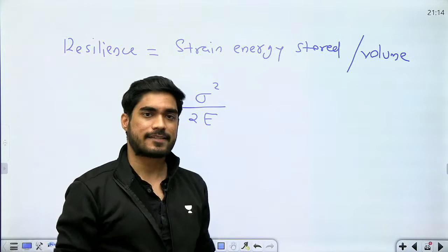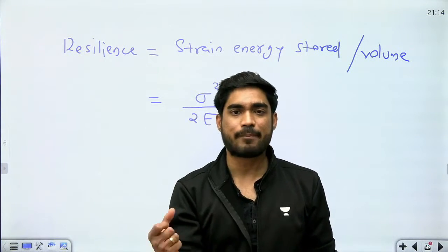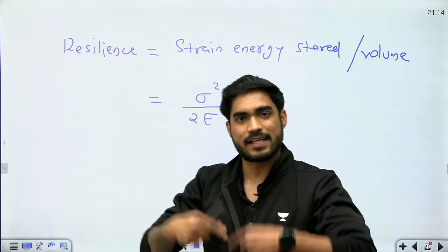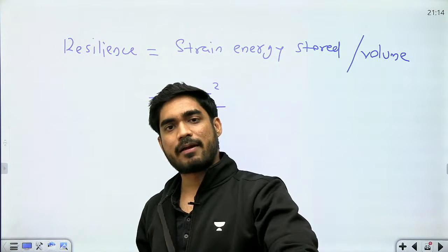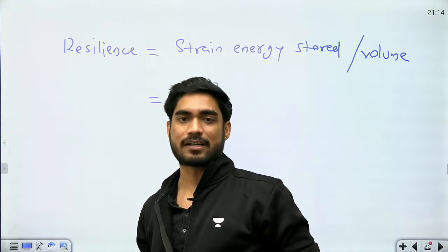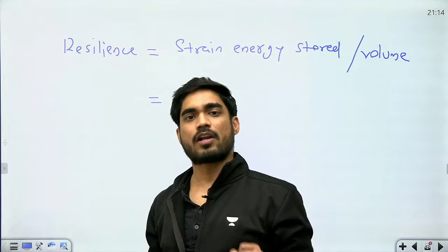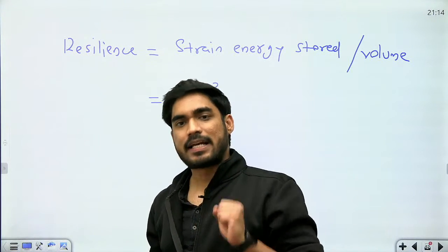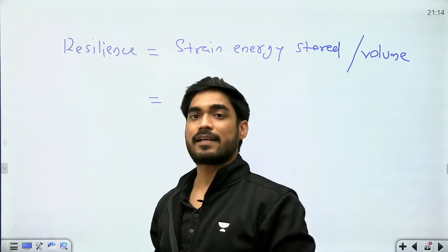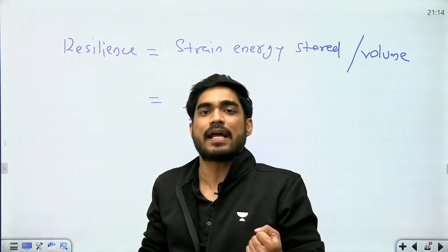So in that case, the strength of the body depends upon resilience. If the resilience is more, the body will be able to sustain more impact load. If I am applying impact load on a body, how much impact load it can sustain will depend upon its resilience, its ability to absorb energy.